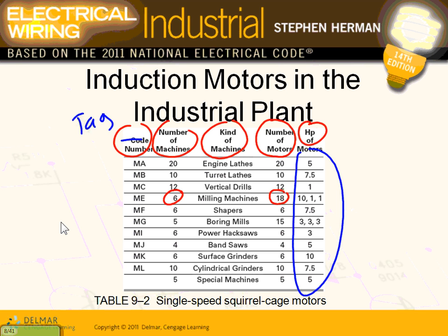And also here the horsepowers. Can I get you to understand that some machines, look at this machine here, each one of them has 3 motors? We always think a machine is one horsepower, but some machines have multiple motors running them. Any questions, guys, about these? And look at all of them, what type? Squirrel cage induction motor. To sound intelligent, if anybody asks what type of motor should we use for this process, 3-phase induction motor, squirrel cage. Done. Any questions, guys, about this?